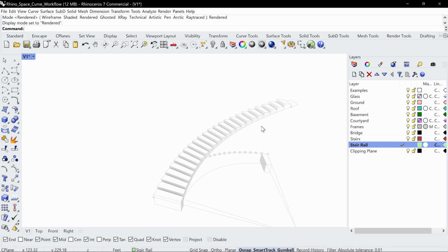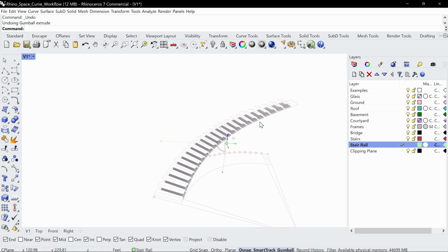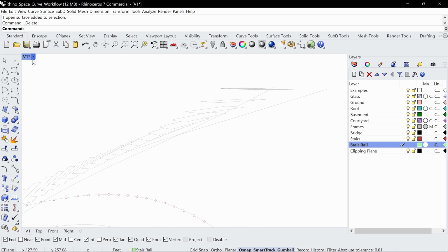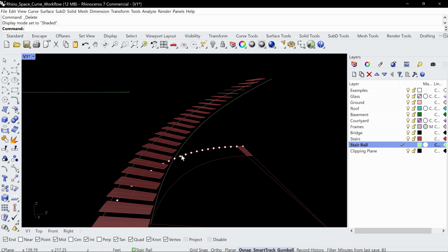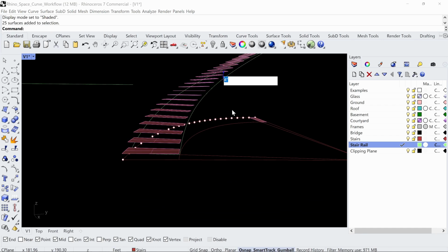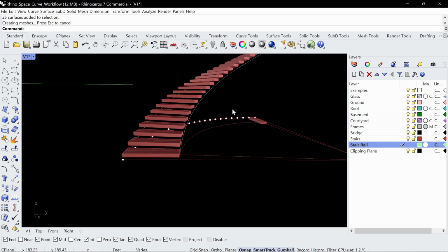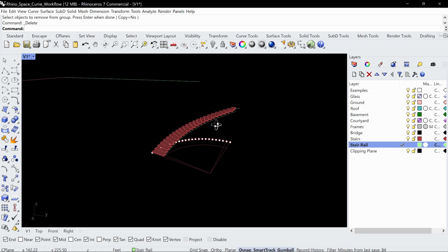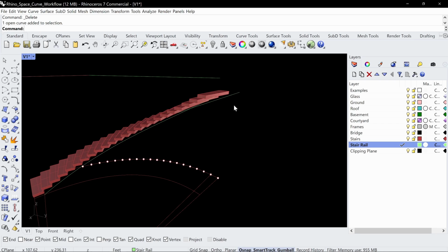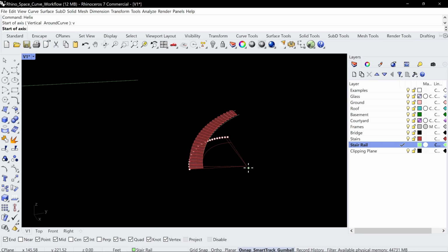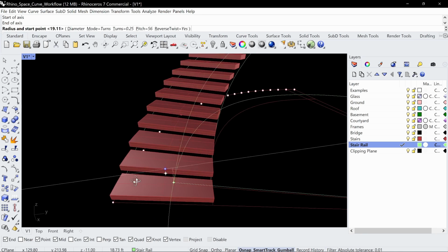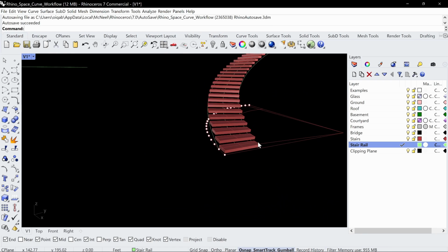So let's go ahead and undo this. I just want to show you all these methods. Let's stick to this one. This looks clean. And we'll extrude this down -4 inches. Like this, right? Remove from group. We don't need this. And then let me bring back the center one. The middle one right here. It is right here, this one.